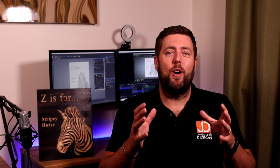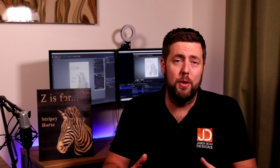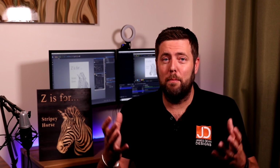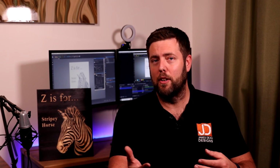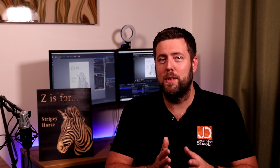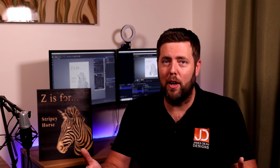Now, a common question that often comes up is, what V-bit should I use? The truthful answer is, well, all of them. It depends on the particular job you are doing. You may want a nice wide cut that is shallow, so you may go for something like a 90-degree V-bit. But equally, if you're doing text and you want nice depth to it, you might go for a much more acute angle like a 20 or 30-degree V-bit.